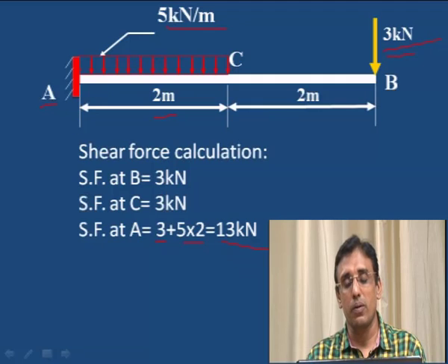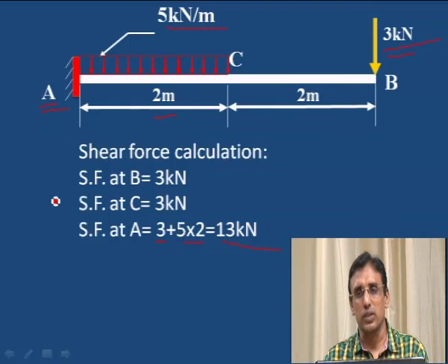Whenever we solve a problem, we can observe that in all cases the shear force is maximum at the fixed end. That is what you have to observe. That is because all the loads are added together, and we get the maximum shear force at the fixed end.